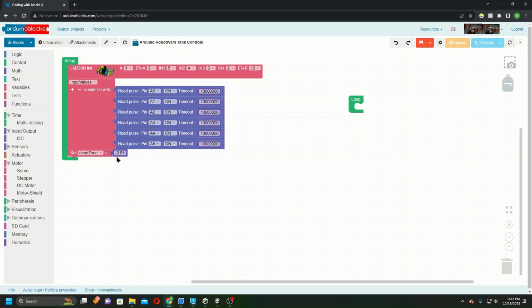I've set this to negative 0.05 here. That's a value that I found works great with the controller that I have. Each one of you, when programming your controller, will want to test it out and find a value that works well for you and eliminates the jitter. Normally, when you see dead zone values inside your programs, it's always a positive value, never a negative value. I put a negative value there for a couple of purposes, and I'll explain that once I get to it.